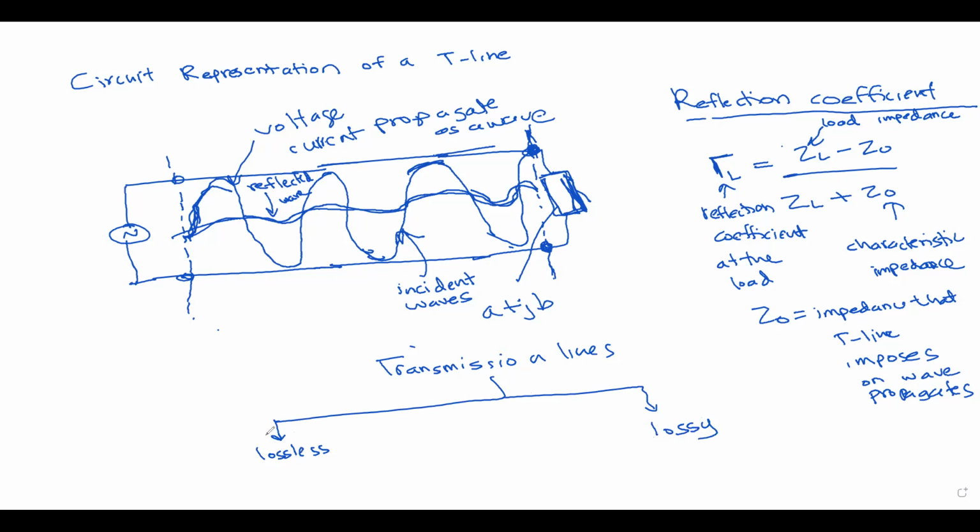So the reason is that once we are sending very high frequency signals along the transmission line, we assume that the amount of attenuation that happens per unit length is considerably low. So the attenuation is happening, but the attenuation that happens is considerably low. So therefore, for high frequency signals, we are considering that the transmission lines act as lossless transmission lines. Okay, so based on that assumption, we are doing the rest of the calculations for the transmission line, right?